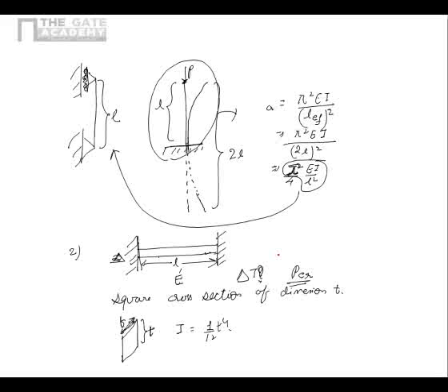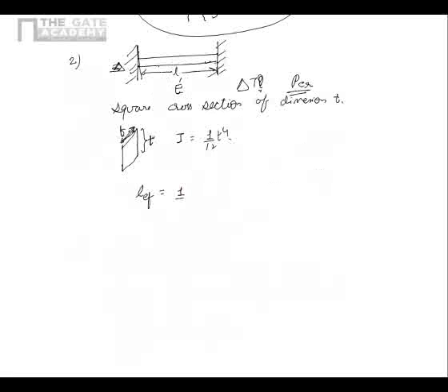now see that this bar is a fixed bar. In a fixed bar, the effective length is half of the original length of the bar. So please remember that in case of fixed condition, this is the thing, because in fixed condition the ends are not supposed to rotate. So when it buckles like this, the length is effectively from here till here only, which is like a simply supported thing. So effective length is half of the total length of the bar.